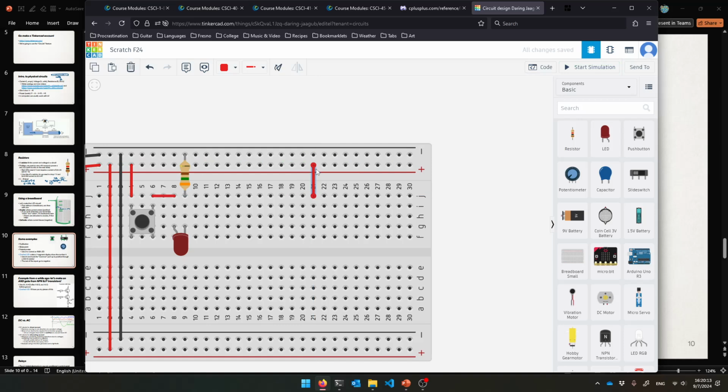So give me positive, and then give me a slide switch, and then I guess if I want to do it like this, then I'll make it so that this is the side that's on. Okay, so left means on, right means off. Because if it's on, it's going to connect this guy to this guy, and so I want to take power to here, let's say, and then I'll bring in an LED, rotate it because it needs to go to the anode part. So if it's on, it's connecting these guys to this guy when it's in the left position. So power is flowing from here to, oh, sorry, we need to hook into the anode, and then we can do the same thing with a resistor. Resistor to negative.